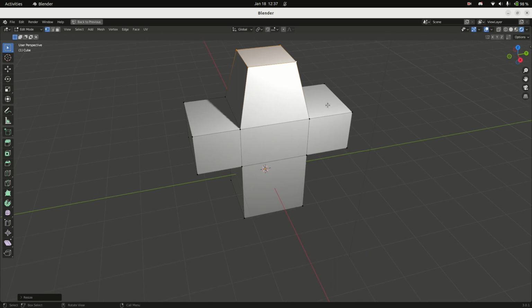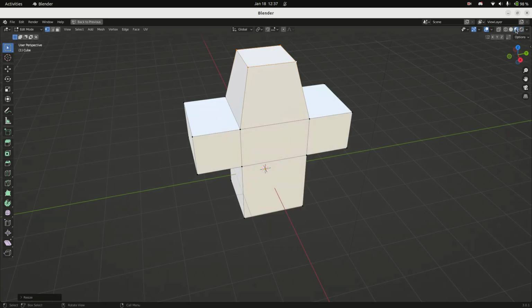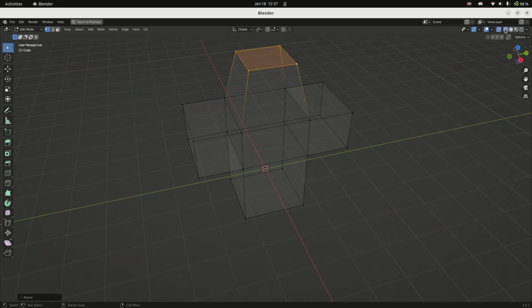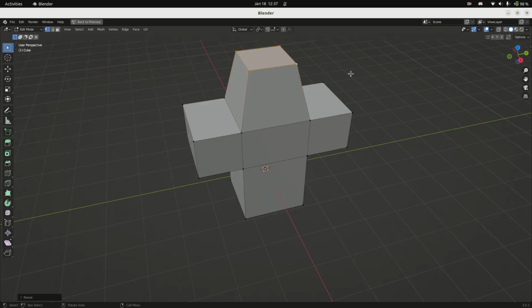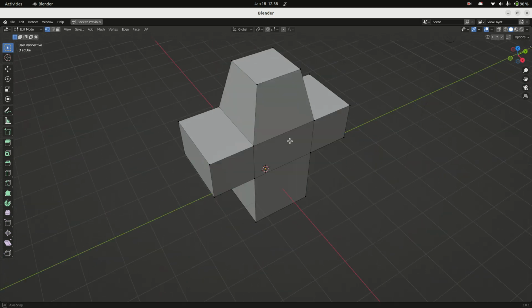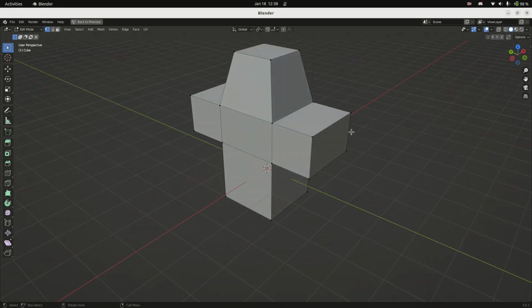It is slower and more likely to cause a crash. Even using the textures, there's no textures mapped here. It doesn't make sense to even work in this. These two, wireframe and flat shade, are the ones you're going to want to do most of your work in. Now, as we start making things that are more complicated, sometimes I want to make sure that I'm only selecting what I'm seeing. So I've got another tool, the circle tool, C. I can paint selection, or I can hold shift and I can unpaint my selection.